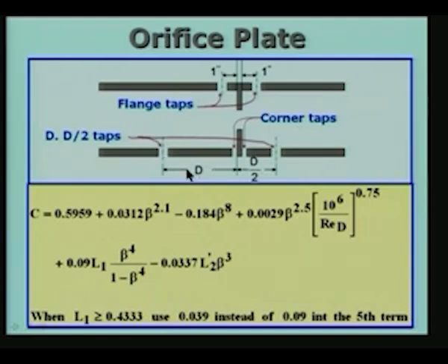So, depending on the range of the pressure difference which you are going to get, you can choose the proper pressure measuring device, either a manometer, or, for example, we have already seen an inclined tube manometer if the pressure drop is very small, and we can choose the manometric liquid suitably so that it gives you a large reading and so on and so forth. This is already something which we have seen.